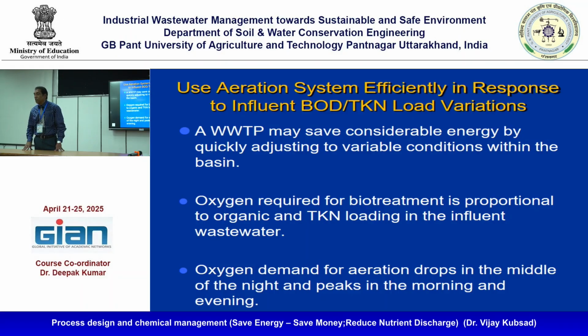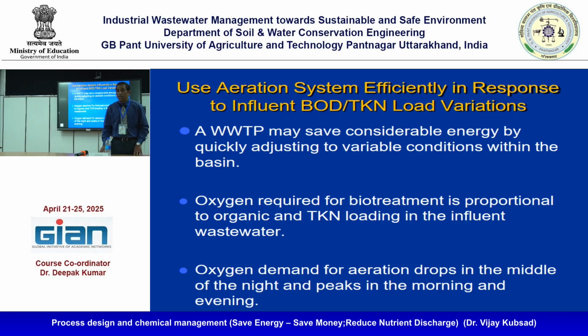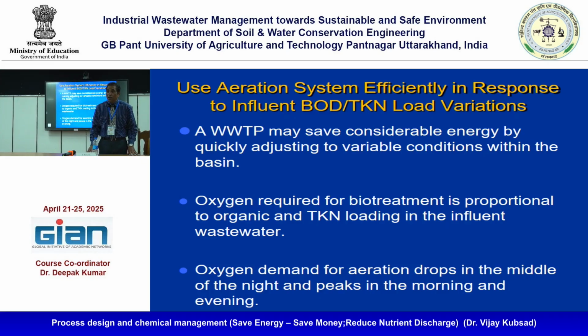Then you will analyze whether there are any inhibitors in the wastewater which are preventing treatment, which you have not thought of before. It may be entering the system. Do analysis. You take a sample, do priority analysis, do other analysis and see if somebody is discharging something which we are not able to track. Why is efficiency reduced? Those things have to be analyzed continuously. That is only possible by doing analysis and having proper training, proper design.